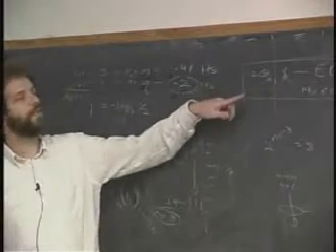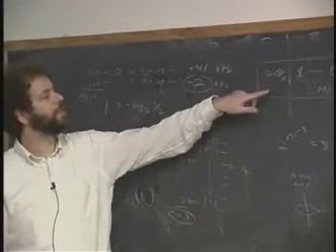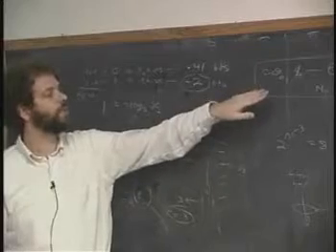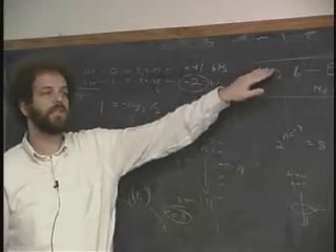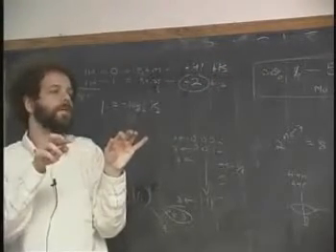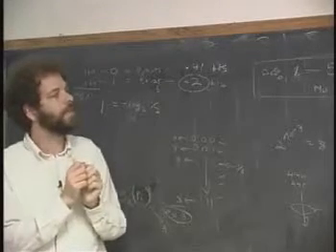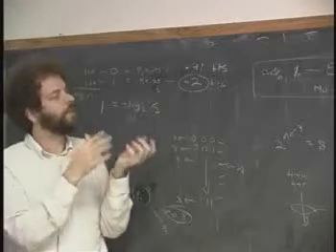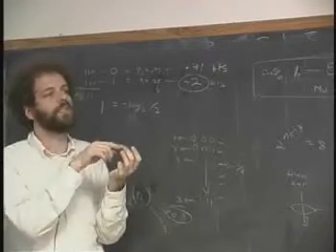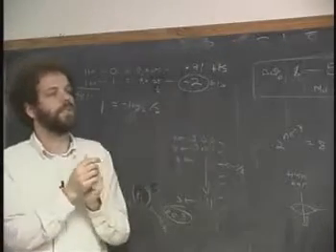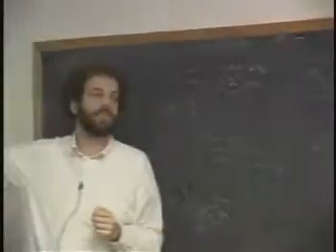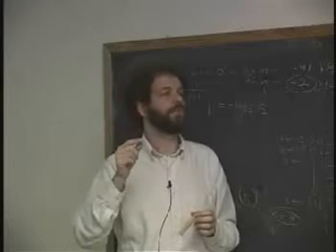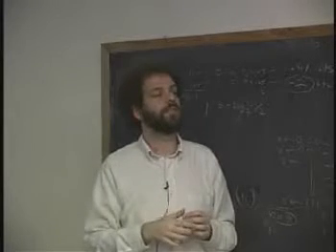And in general, for every, I forget how many bits, but this has around 20% more bits in it than this does. And whenever a word is stored into a memory like this, it computes an error correction code and adds 20% more bits. And that allows any single one of those bits to go bad. And then the reader looks at that and says, aha, I know that this one is bad, so I'll fix it. And then it gives you the right data out. Exactly as when we just read the sentence that was up on the board, even though some of the letters were wrong, we were able to fix them because of the redundancy of the English language.